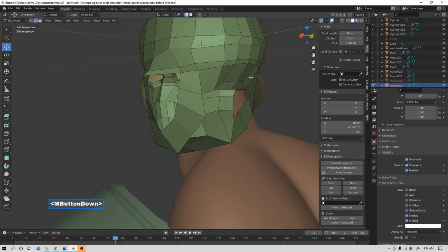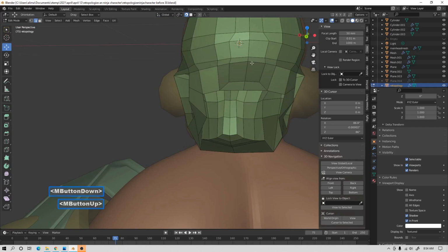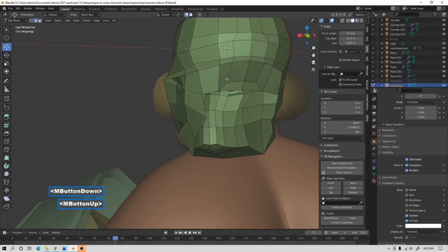There's multiple ways of doing it, which is one of the things that can be difficult about it. This thing right here is good to know. A lot of times with retopology, what you're doing is trying to figure out how to match up what to what, and then you'll often have too much geometry. So this, where I came down and then pushed to the side here, is a pretty effective way. There are other ways as well, like reducing the geometry. Also, this could be positioned higher. For this scope, there's a Ninja hood that goes over this, so I think it's fine for here.